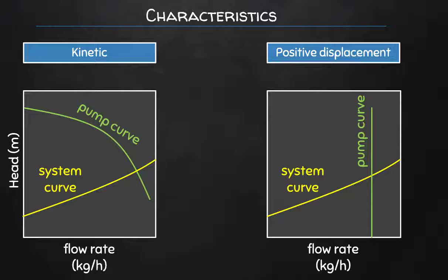So you can imagine that positive displacement pumps are very good at selecting a certain strict velocity or flow rate through the system. Note that a shift in the system pressure can be obtained, but you can also shift the system curve back and forth, and so you can select a flow rate and you can also specify a higher or lower operating pressure based on constructions such as a control valve, which would block the movement of the fluid and increase the pressure until the pressure drop across the control valve becomes stable.